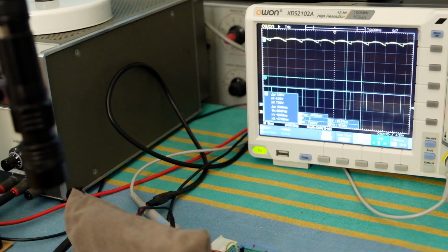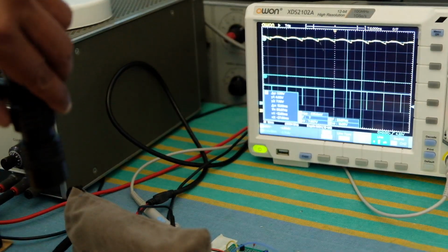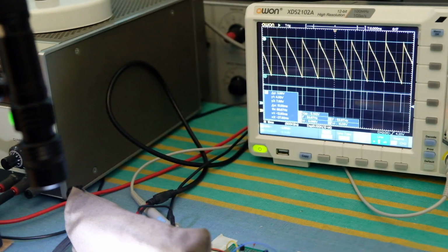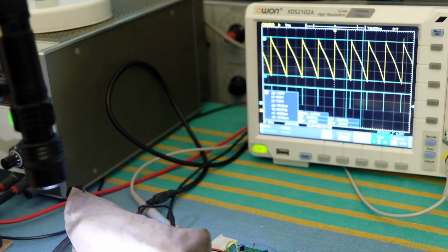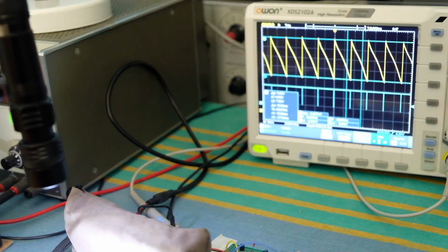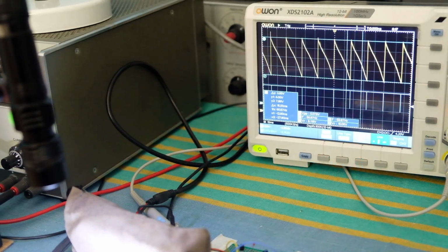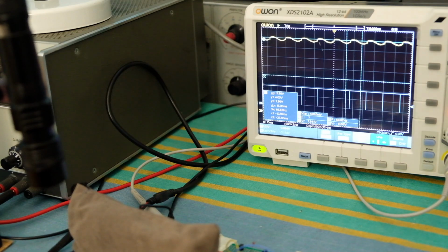Now I'm going to do the green LED, and let's see what happens here. Okay, we have a very good swing, almost 4 volts, and it's linear for the most part, except towards the middle it starts to droop off a little bit more quickly. Other than that, I think it's a very solid linear output from this green LED. And now for the red LED.